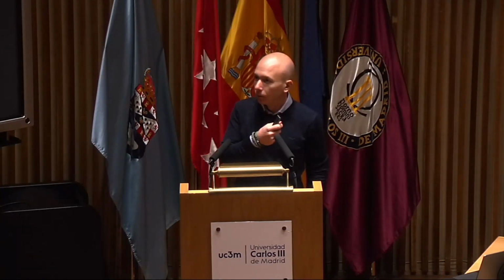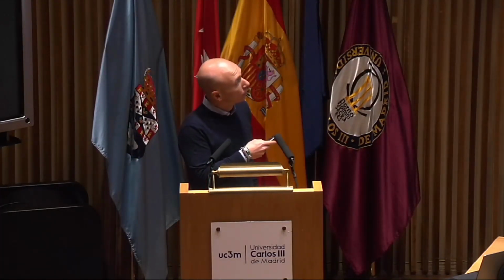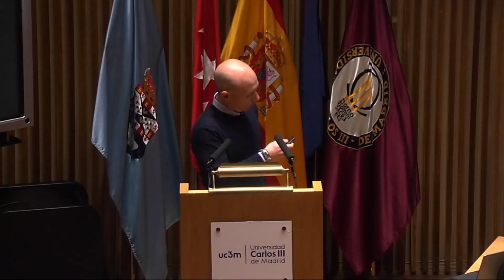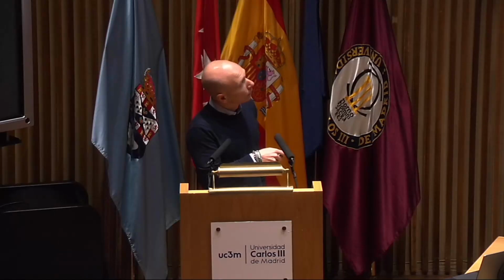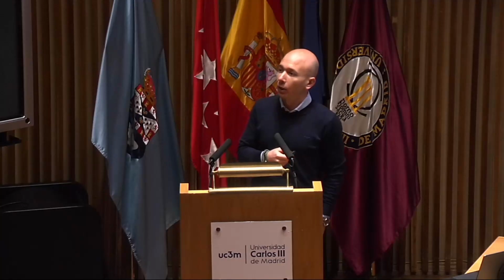So the peak that we could see in damping at about 1,400 hertz was due to the presence of the liner. There was a blue outlier in this damping; you passed the slide already, I think it was 2 or 3. Yeah, exactly. You have a peak in the normalized resistance at 1,400. This is an issue of the measurement technique you use.